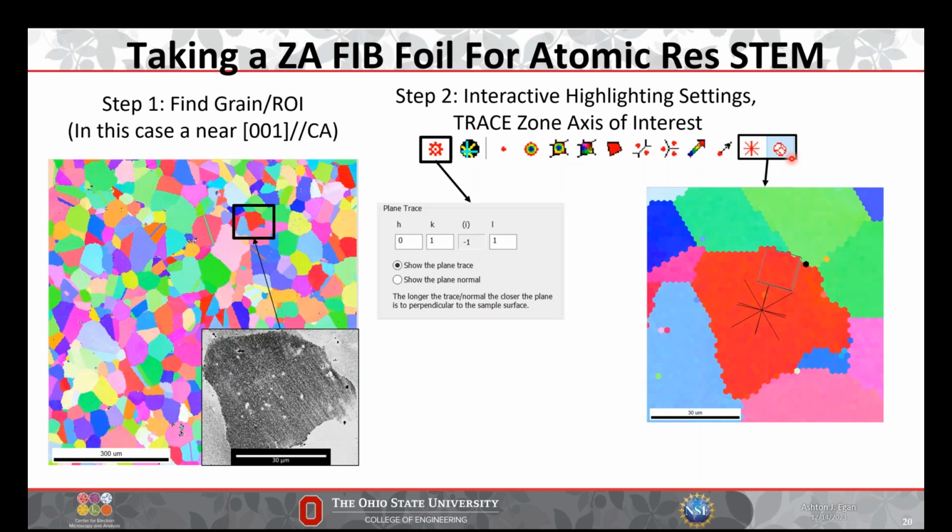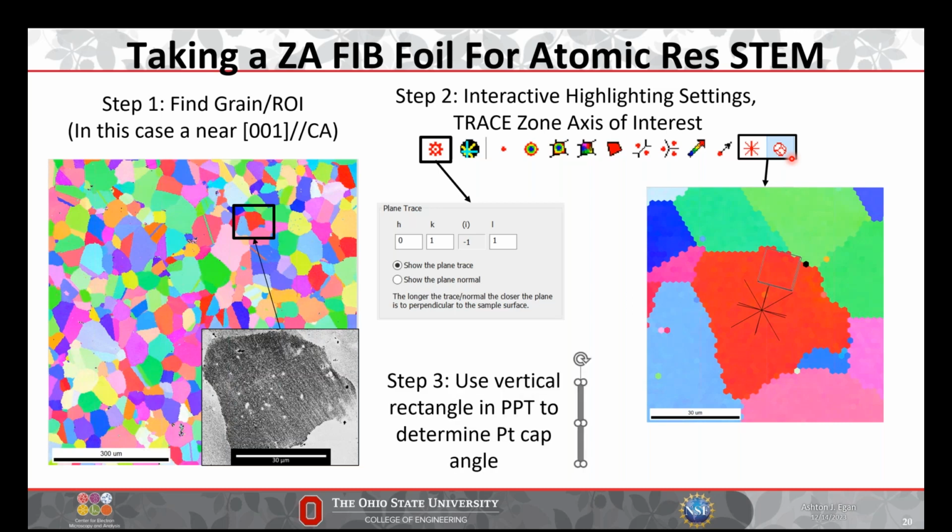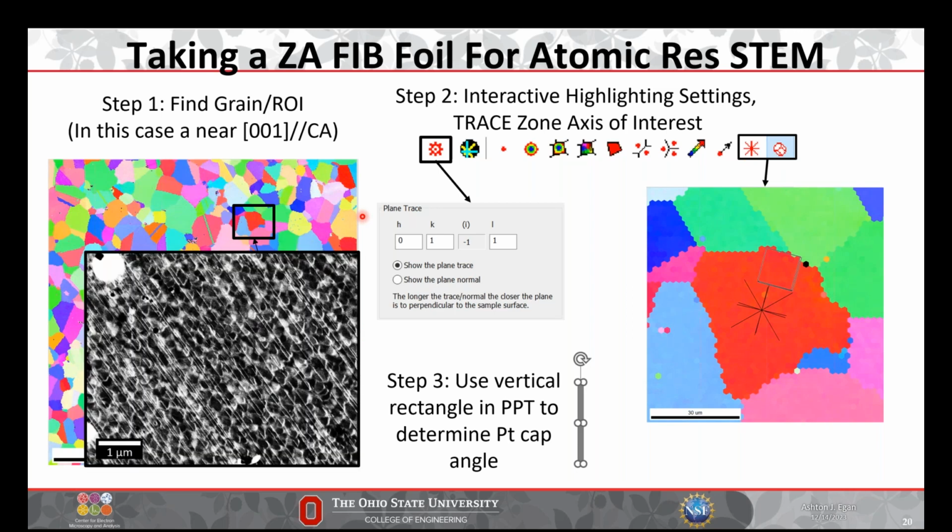And so which one do we actually take? Because there's two, right? And now we kind of have to think about our ECCI orientation, and how these are laid out in real space. And so basically, if we look at the traces of these deformed traces, or these stacking fault microtwins, they're diagonal. And so to look down the edge of them, we would have to lay the platinum along this 011 type